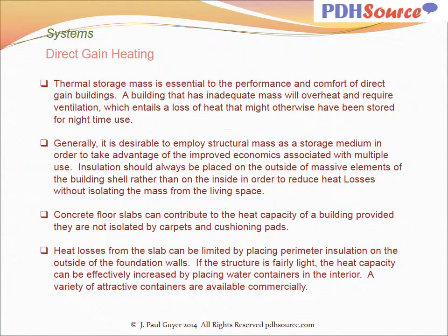Thermal storage mass is essential to the performance and comfort of direct gain buildings. A building that has inadequate mass will overheat and require ventilation, which entails a loss of heat that might otherwise have been stored for nighttime use. Generally, it is desirable to employ structural mass as a storage medium in order to take advantage of the improved economics associated with multiple use.